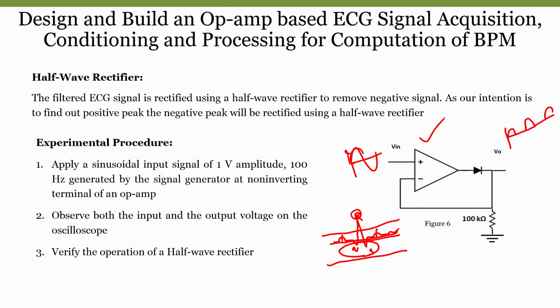If we can detect this particular peak, our problem is solved. So, in order to detect that, we are using a capacitor which stores the highest voltage, but how do we create a threshold? And if I can create a threshold and compare the output signal with the input signal, then when you do the comparison, whichever is the highest, I can decide it.